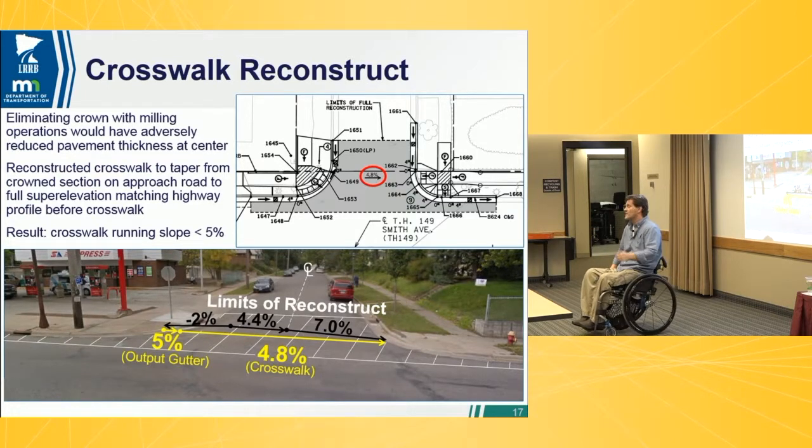Because of all those reasons I talked about, pedestrian cross sidewalks and everything, but even from a roadway standpoint, if I've got a hill going downhill like this, and I want to put a cross slope in here of my sidewalk corridor, I'm falling from a hill to a river and my road is paralleling it. If I put this crown section in, I'm fighting the lay of the land over here, and obviously I'm making the pedestrian facilities worse, but I'm also making all of my road tie-in facilities worse. So don't even fight it.